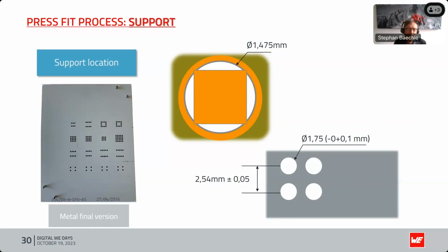Because every PCB looks a little bit different, and you can also have SMT components on the downside of the PCB, you then need some carvings in the support so as not to destroy those elements on your PCB. That means every support location is a little bit different for every PCB. But we can recommend you some companies which are able to do that.